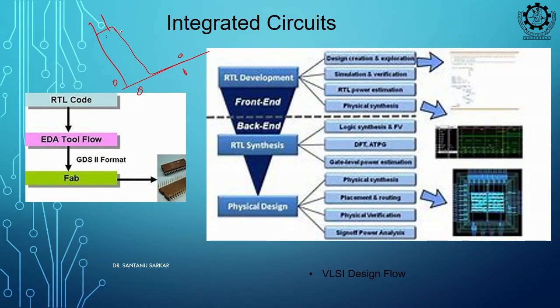But this is your linear phase. In analog design, you are working in this, right. Here you work as an amplifier, but in digital you are working here, and in this phase you are having output 1, in this phase you are having output 0. This linear region you are not interested in, you say this is a do not care, right.